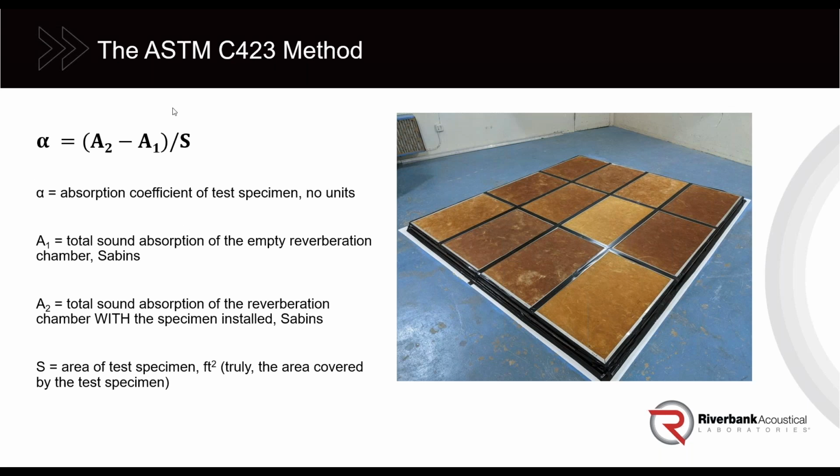Now, that term is not technically correct. It is not actually an energy absorption coefficient. However, that's the way we have used that term in this industry. It's very traditional. So, sound absorption coefficient. For the most part, 1.0 is seen as 100% absorptive, but really what it means is you have 1 sabin per square foot. If you have a sound absorption coefficient of 0.5, that's sometimes seen as being 50% absorption, which is approximately correct.